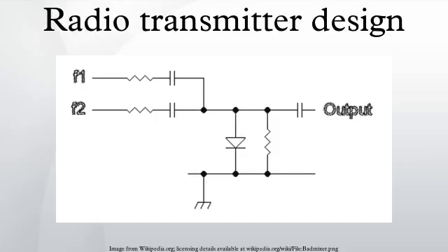Instability and parasitics. If a stage in a transmitter is unstable and is able to oscillate, then it can start to generate RF at either a frequency close to the operating frequency or at a very different frequency. One good sign that it is occurring is if an RF stage has a power output even without being driven by an exciting stage. Output power should increase smoothly as input power is increased, although with Class C, there will be a noticeable threshold effect. Various circuits are used for parasitic suppression in a good design. Proper neutralization is also important.